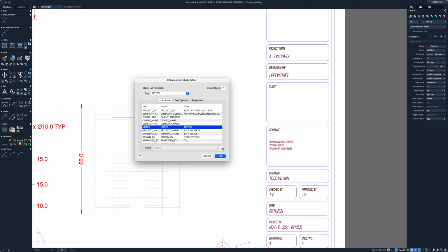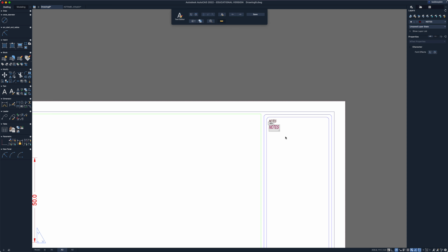And we're just going to go to this notes section right now, which is up here, and we'll add a few notes. So start off with a little dash, and we'll get rid of that text right there, and we'll write: all dimensions are in millimeters unless otherwise specified.